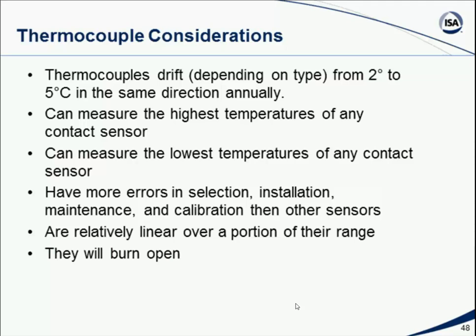The thermocouples also are not necessarily linear. Most thermocouples have a curve that is sort of S-shaped. Over the middle of their curve, in other words, the middle of their range, they're pretty linear, but at the low end and the upper ends of the range, they're nonlinear. So if you have to operate over a wide range, then you have to have some type of curve correction, usually done with some type of a breakpoint table.